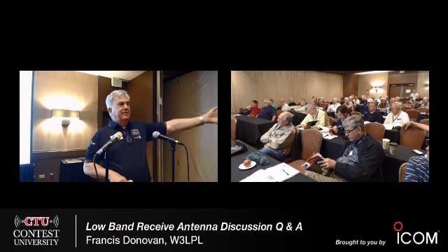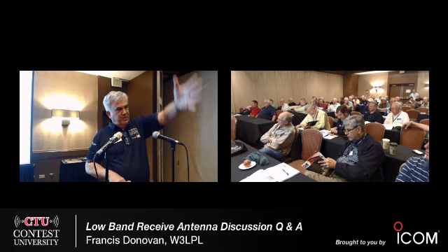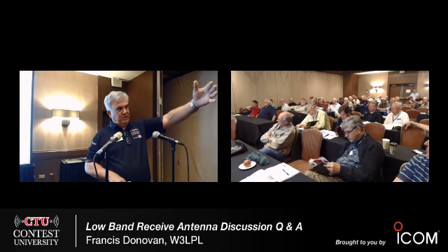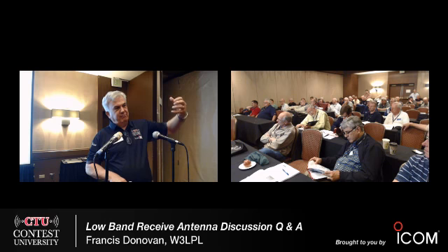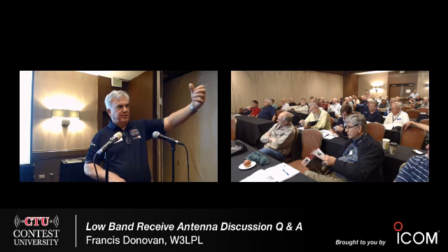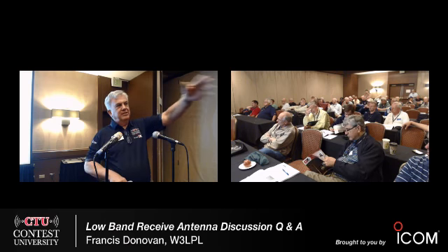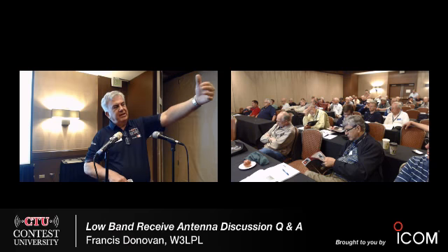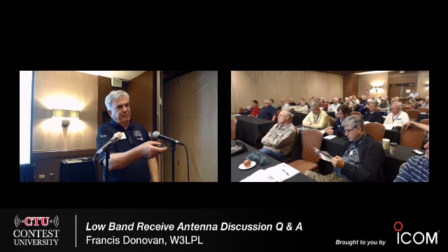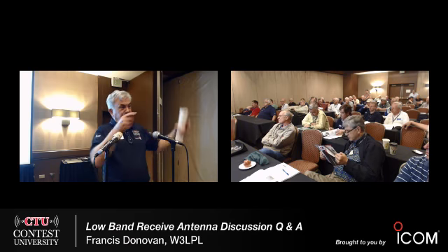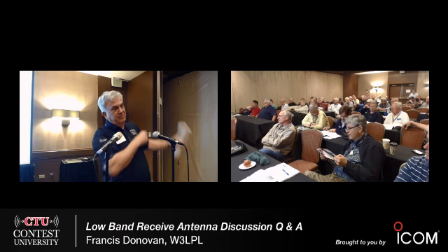But when you're pointing into that telephone pole with a vertical wire in front of it, signals will be received by that vertical wire and re-radiated, just like the parasitic element on your 20-meter beam. Signals from other directions are going to get re-radiated into the main lobe of that high RDF array. So even if you can't get a couple hundred feet from that power line, you're still going to get the benefits when you point it away from the power line, but not when you point it into it.